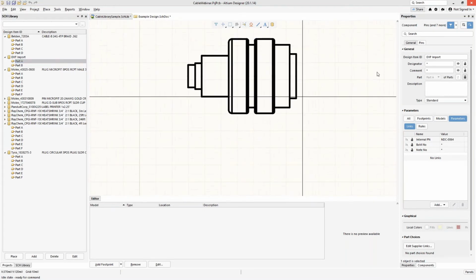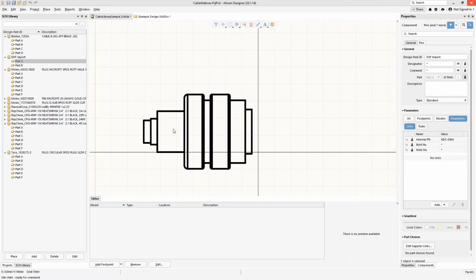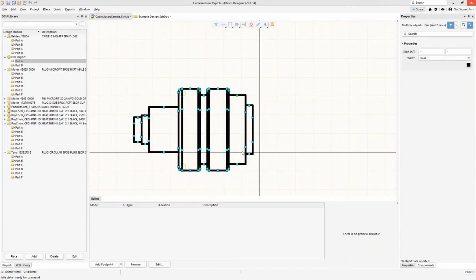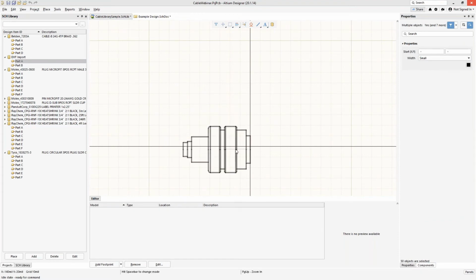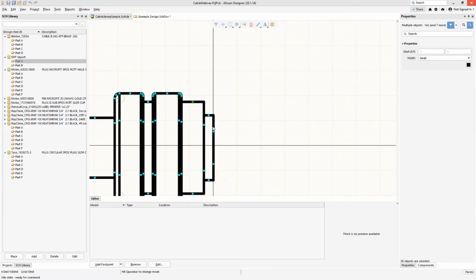The one recommendation I will make is that, again, these might come in through metric, but it doesn't really matter other than the fact that you want at least one face to be on the 100 mil grid. So here I would try to move this one over. I will click and grab it here, and I would try to get it onto the grid, just so that when I do the Bezier curves, they will line up with the grid over here and they won't be overshooting it or sticking out. And sometimes you do have to play with this and drag it in a little bit just to get it corrected onto the grid there.